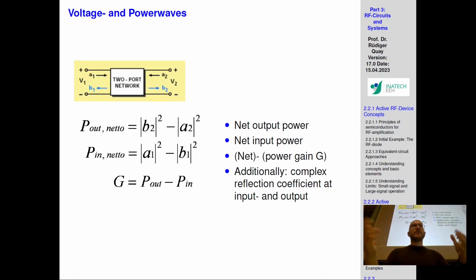The gain is in dB. The power is in dBm with reference to milliwatt. dBW is with reference to a watt, but we usually work in dBm. In RF, yes, in the lower bands you do have mega. You can even generate ranges of kilowatts, but usually at 100 gigahertz or so forth, you will not have that.